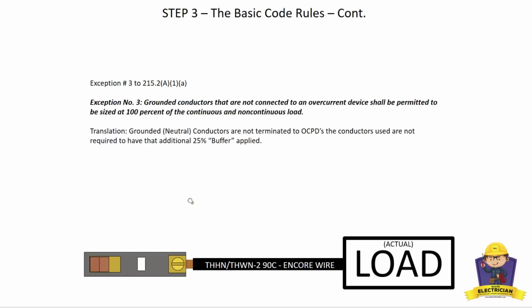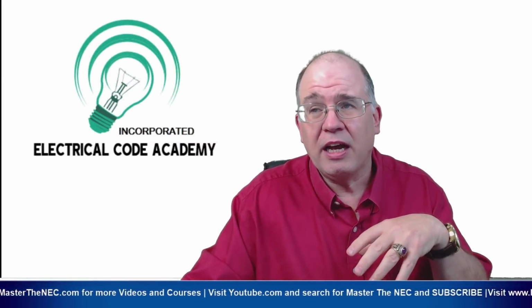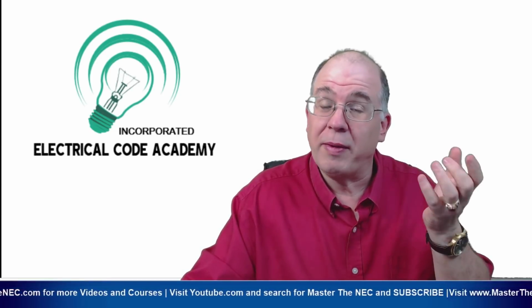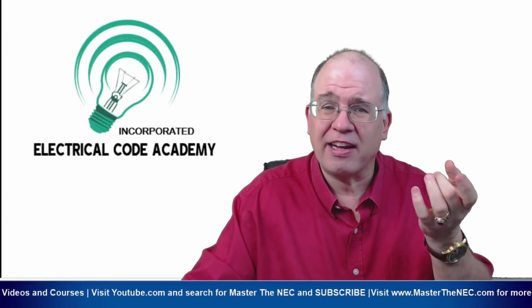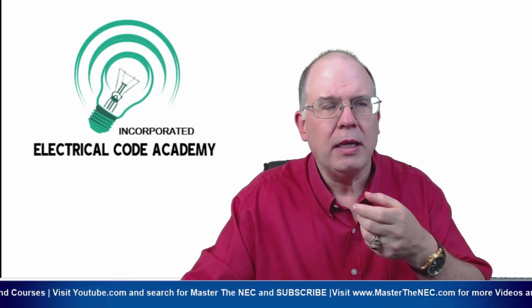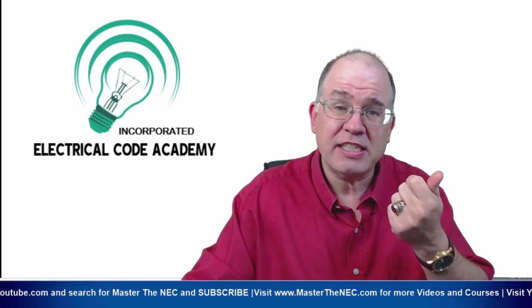Now, exception number 3 is reminding us, okay, grounded conductors that are not connected to overcurrent devices shall be permitted to be sized at 100% of the continuous and non-continuous load. All right, well, because the terminations for the grounded conductor are not limited by a terminations issue, and generally the terminal itself might be 90 or whatnot, just the terminal. It's not on any device like an overcurrent device or a piece of equipment, or an appliance, what have you. So you're usually going to be limited to 75 degrees C here.